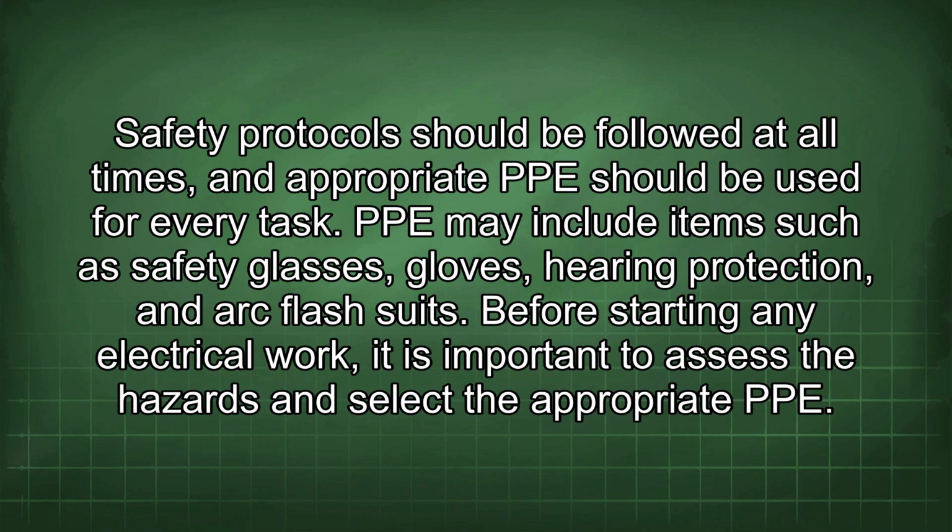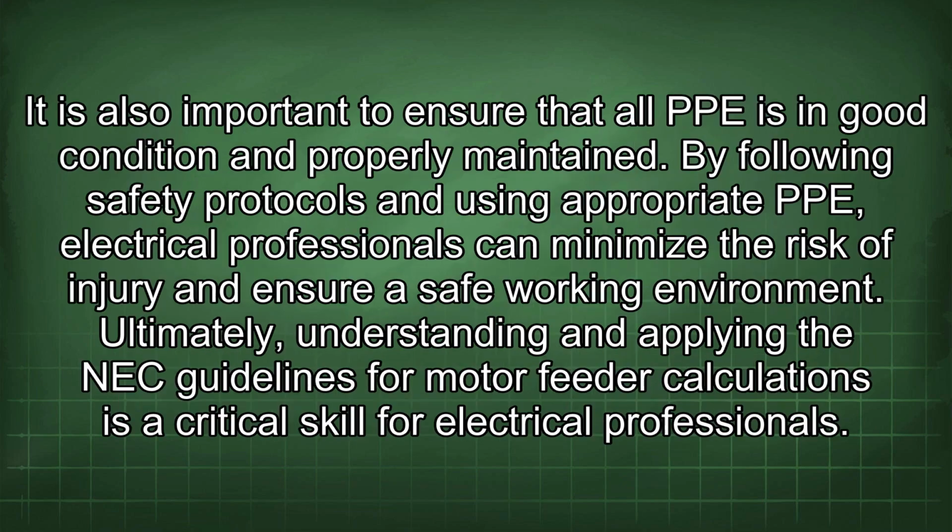PPE may include items such as safety glasses, gloves, hearing protection, and arc flash suits. Before starting any electrical work, it is important to assess the hazards and select the appropriate PPE. It is also important to ensure that all PPE is in good condition and properly maintained. By following safety protocols and using appropriate PPE, electrical professionals can minimize the risk of injury and ensure a safe working environment.